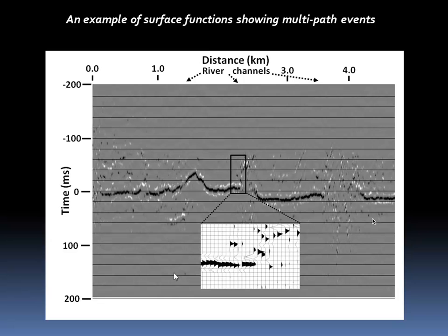On the bank of the river, everything is frozen solid to the surface. As you move out into the channel, then you run into the soft melted stuff beneath the water, and you wind up with two actual transmission paths for seismic energy, the slow one through the mush and the fast one through the edge of the channel. So with this indication of that, there's no way to correct that with a single shift. The only way you can correct that is to get an inverse filter and deconvolve it.